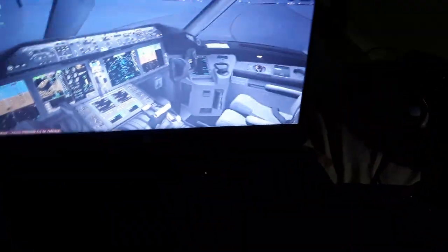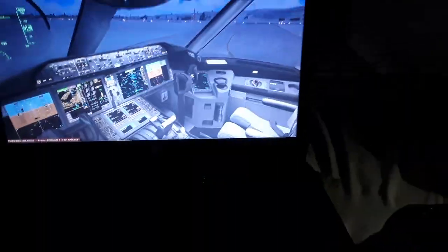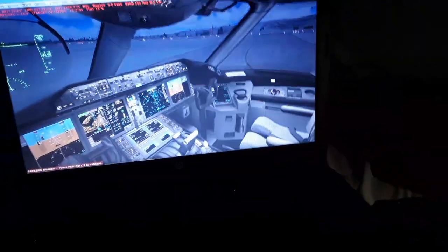So I will show you now the flight management computer very quickly inside the aircraft, and a couple more controls and screens, and we go for full flight. So we need to set up the flight management computer over here. The flight management computer will input all the data we need for this flight. Also it's going to be flown with the autopilot flight director system panel. If we connect the autopilot, it's going to follow the flight management computer, the flight plan I'm going to create right now.